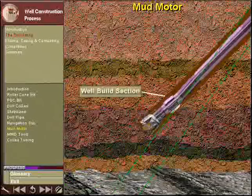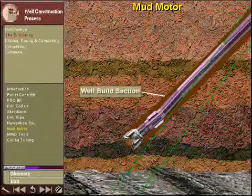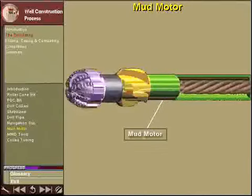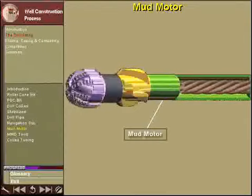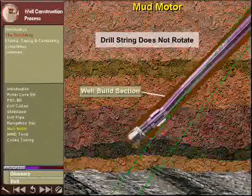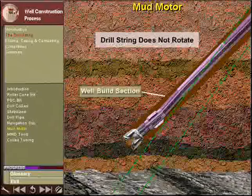When the build section of the well is reached, the rotation of the drill string is stopped. The circulation of mud drives the mud motor, and the drill bit still rotates. The rest of the drill string, however, does not rotate. This allows the build section of the hole to be drilled.